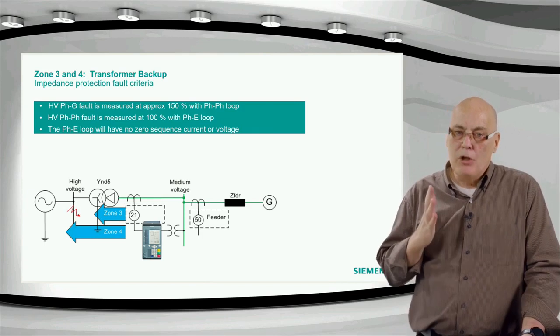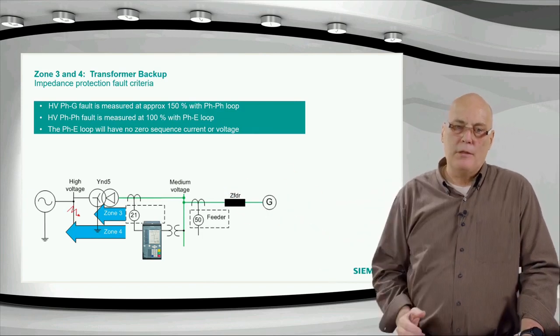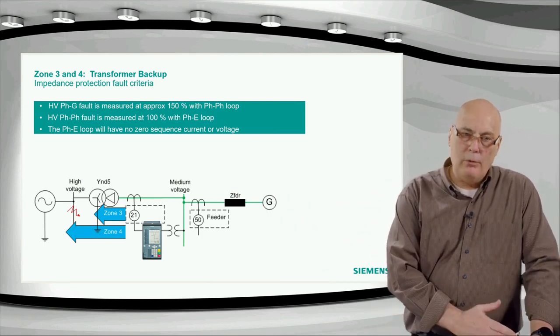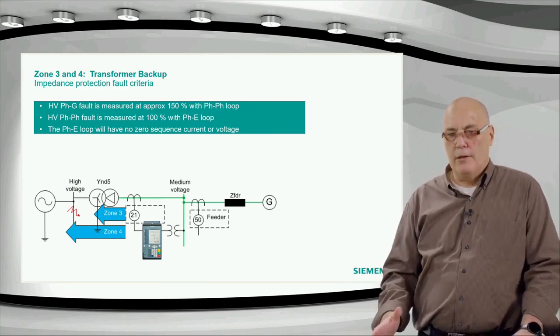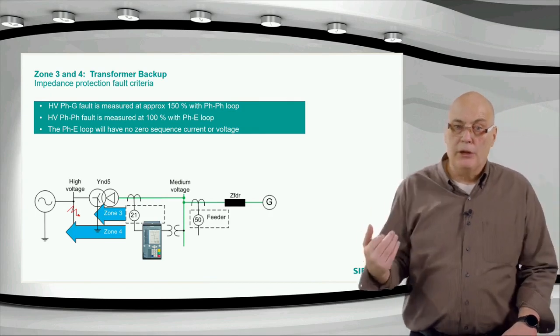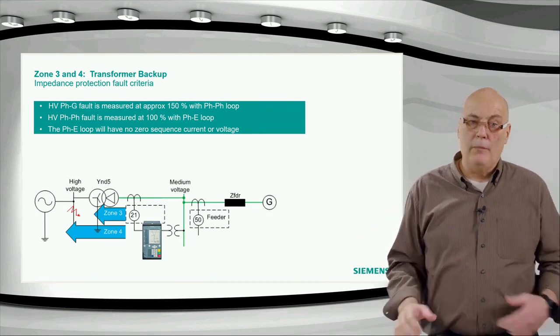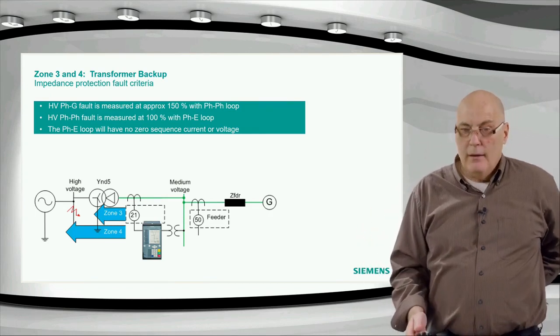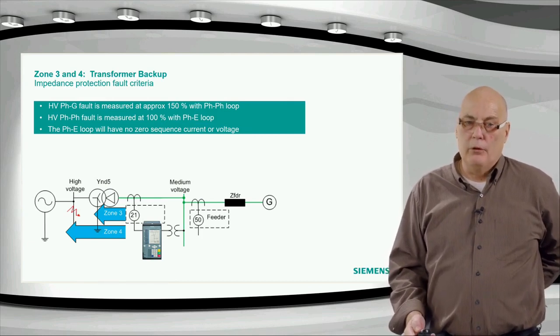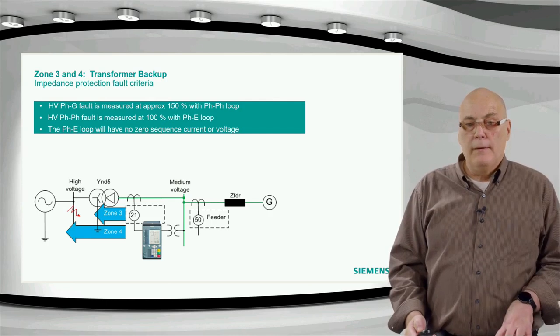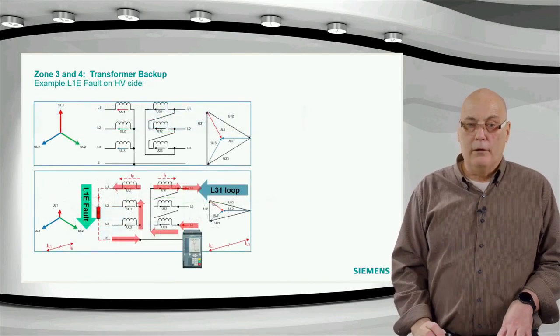So we typically will see on power transformers that if you have a ground fault on the one side, the zero sequence will not be coupled through to the other side. And remember, in our loop selection, that was an important requirement: that we get a single-phase loop, which can pick up only if we have a ground fault detection, for example. So normal distance protection is not always going to be ideal over here.